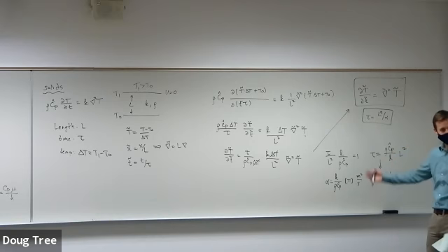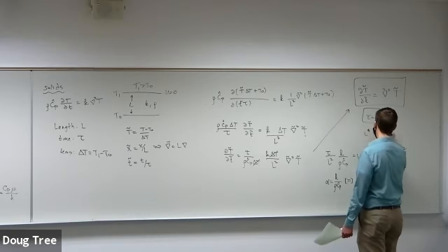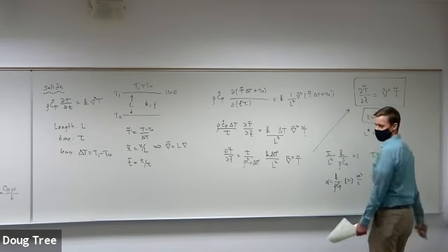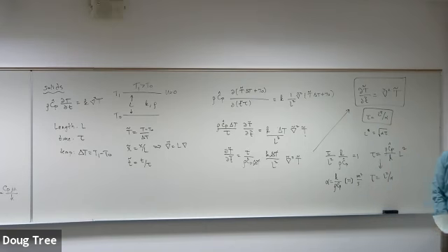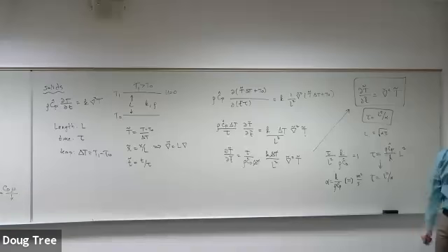Okay, but I can use this to get rough estimates. Alternatively, I can also use this to find the length. The length is equal to the root of alpha tau. So if I want to know how far away something is going to feel diffusion at a certain time, I can pick a time and calculate that length, right?